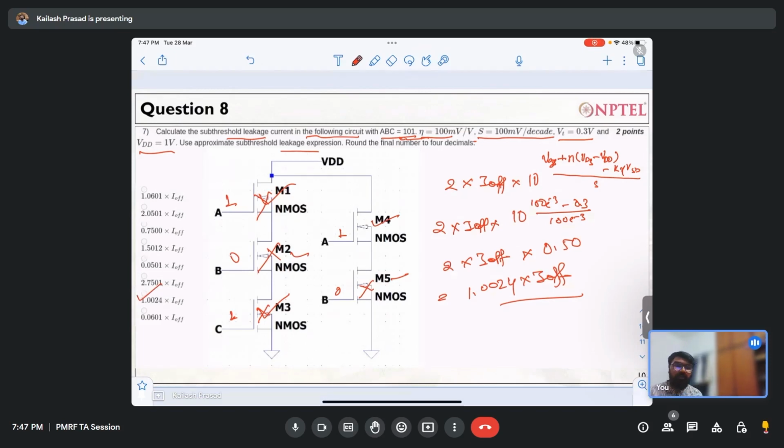So what we have done in today's lecture and in the last couple of lectures is we have discussed static and dynamic power, right? And I'm just repeating whatever I have said. There are two kinds of components of power: the static power and the dynamic power. The dynamic power is only consumed whenever there is a transition, right? There is a transition of an input node, a transition of an internal node, or a transition of the output node. If these three things happen, in that case the dynamic power will be consumed.